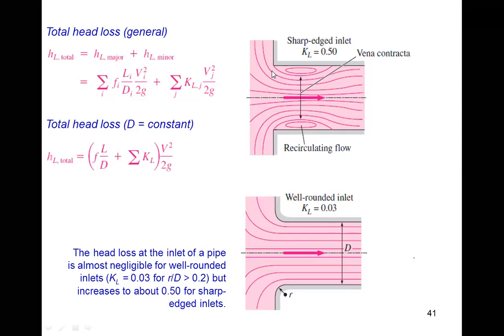Why is it a loss? Due to this change in shape. This is a sharp change here. So the energy losses here would be high compared to the losses here, because here you have given a slight curve. Whenever you turn a car in a long radius, you need not put on the brake and all this. You are easily turning, so the energy is conserved and not wasted. Here you put a curve, so the losses are slightly lower.